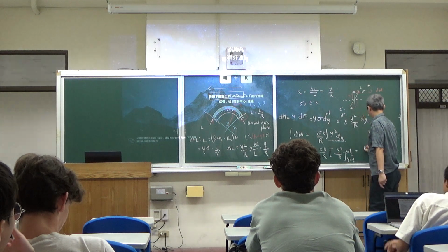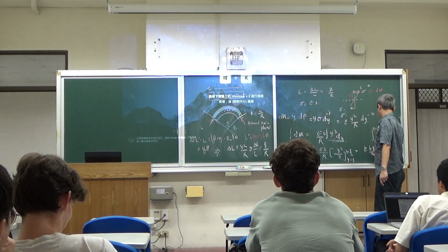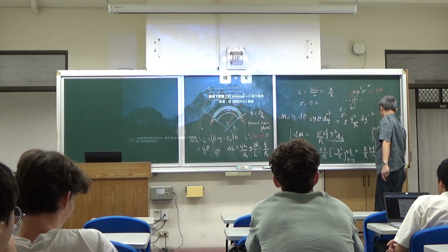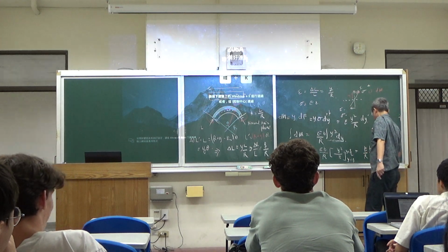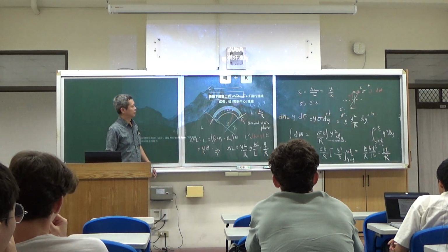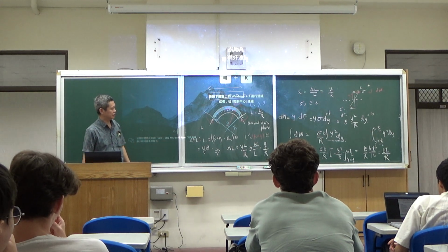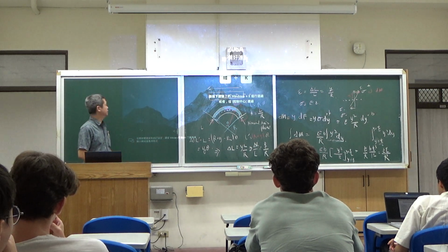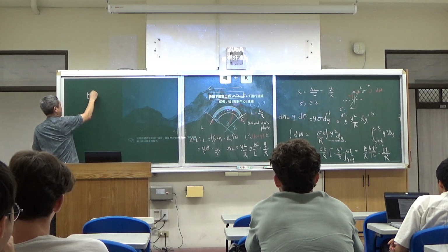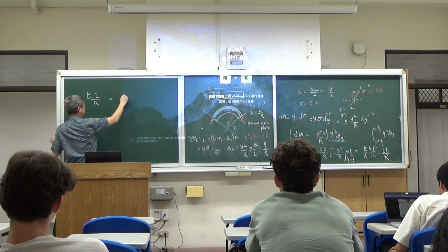So in the end, you have E times t cubed divided by 12 over R. This is what we call EI, flexural rigidity, divided by the radius. Okay, so this is what you have commonly for the beam bending theory. In the mechanics of material, you know this very well: EI over R is equal to the moment.